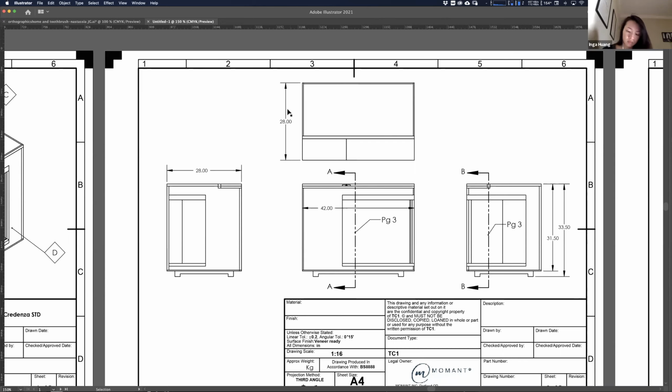So general dimensions to start off. This is one of the things that you definitely want to make sure everyone knows, right? Not just all the title block stuff, which is a given. Everyone should have that pretty much down pat by now. The other thing is these lead lines and showing your dimensions. It's okay if the dimension is right in the center of these lead lines, making sure there's no line going through the number at all. You could opt to put the dimension above the line. So if the line does go through, the dimension is up on top.